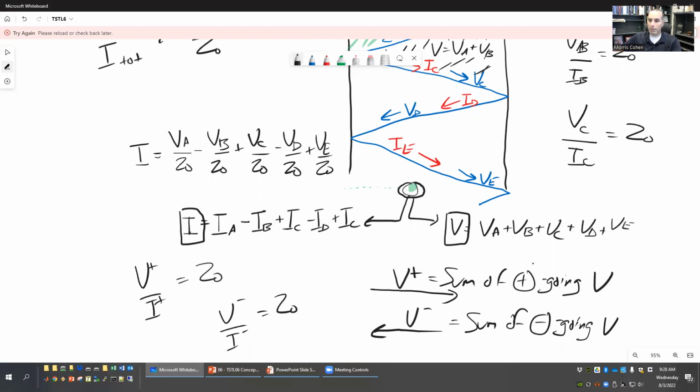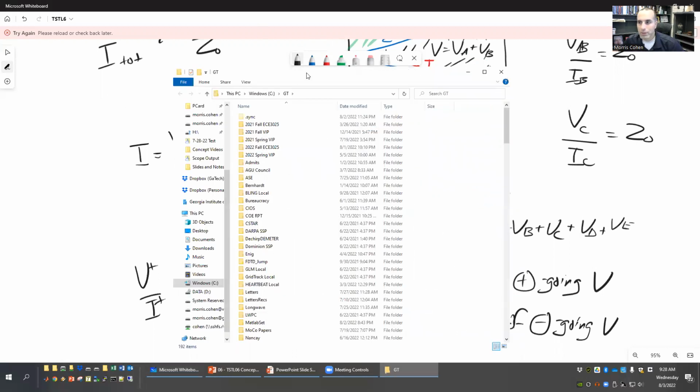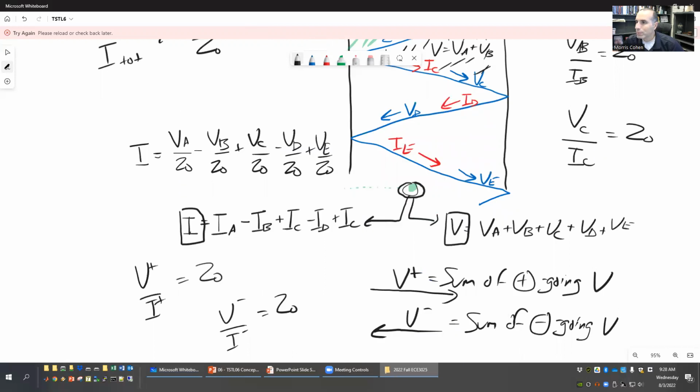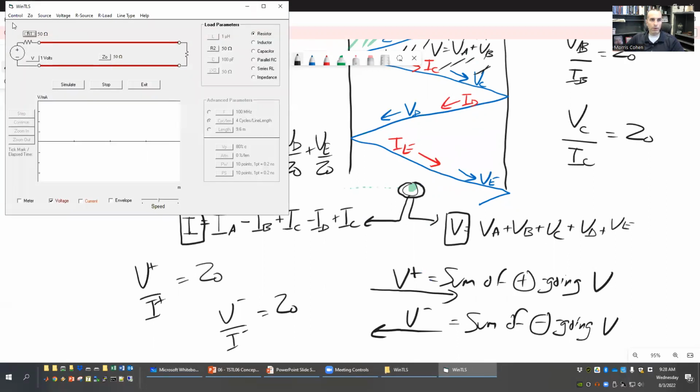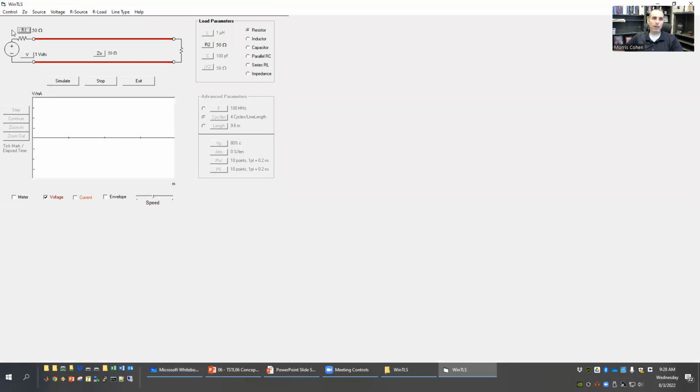All right, so let me just try to visualize this with another quick simulation, just a second. I have to open this beforehand. All right, so I'm going to set a generator impedance of 50 ohms. I'm going to set a line impedance of 100 ohms. I'm going to set a load impedance of 200 ohms. All right, I'm going to press go, and I'm going to let this settle out. Here comes the wave. It's 2/3 of a volt propagating in the positive direction. It reflects with a positive coefficient off of the load.